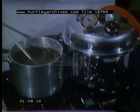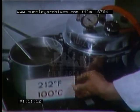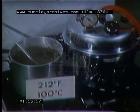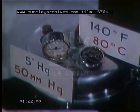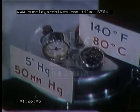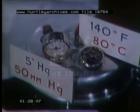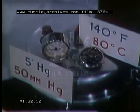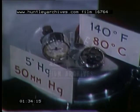Heated in air, water boils at 212 degrees Fahrenheit. The pressure of the air is 30 inches of mercury. But when we lower the pressure in the cooker with a vacuum pump, the boiling point of the water inside the cooker also falls, so that it boils at 140 degrees Fahrenheit. The pressure is now 5 inches of mercury. So, reducing the pressure of a liquid reduces the boiling point.